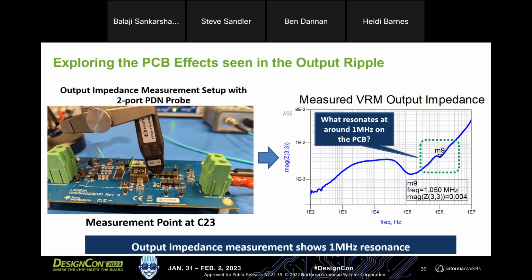In fact, I used the same model for the International Space Station for the bidirectional controllers, which are up around 10 kilowatts or so. It's just a really good model of the plant functions. And so long as we can get the models accurately, you'll get an accurate representation. I think there are 2 things that are really important to remember. One is that a bad state space average model is better than not having a state space average model. So I wouldn't worry too much about it being perfect. I would worry about it being good.